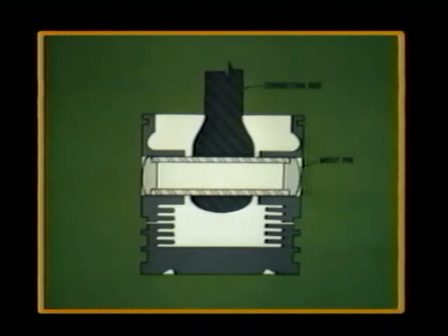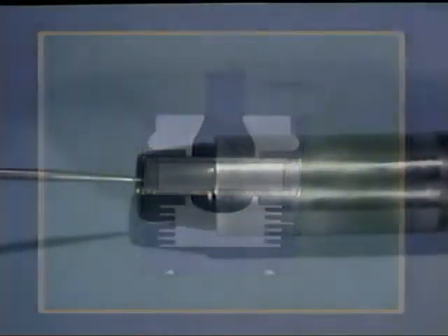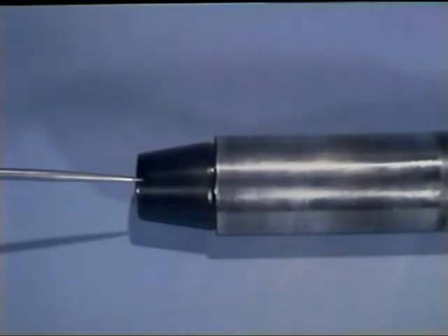The piston is held onto the connecting rod by a hollow, high-strength, highly polished steel wrist pin. This pin, in almost all aircraft engines, is free-floating, meaning it is free to rotate in both the connecting rod and the piston. The wrist pin is prevented from scoring the walls of the cylinders by plugs of soft aluminum or brass, which are inserted into each end.